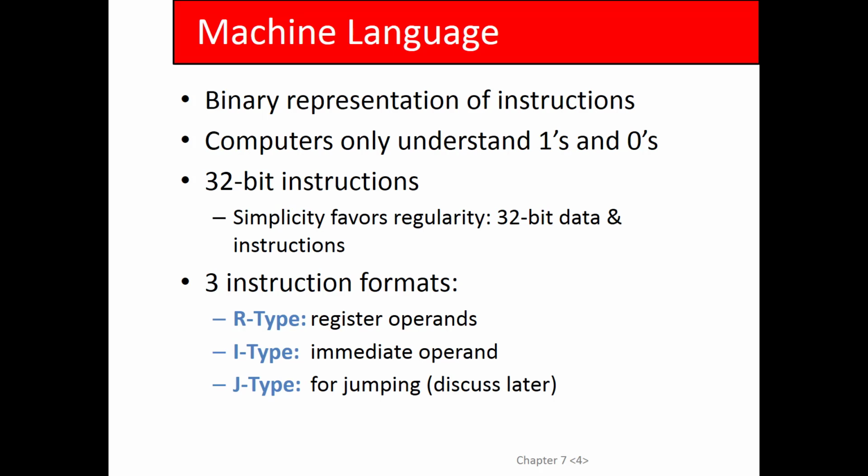That's an R-type instruction, and then you send it back out. I-type is the instructions that do the bringing the data in from DRAM and sending it back out. Those are I-type, so the loads and stores are I-type. I refers to immediate because you need to put an address inside the instruction. So I-type instructions are what brings the data in, R-type instructions are what processes the data, and then you use I-type instructions to send it back out.